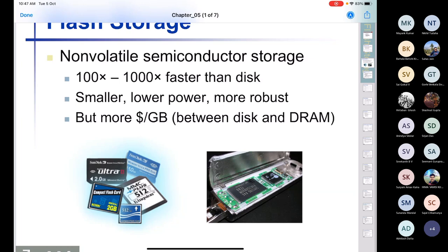They are built by NAND or NOR, two types of non-volatile memory. They work in a very peculiar fashion, by forcefully injecting charges through the gate of a MOSFET transistor. Now, from your electronics courses, rule 101 of MOSFET is that gate current is 0. You start with that assumption.